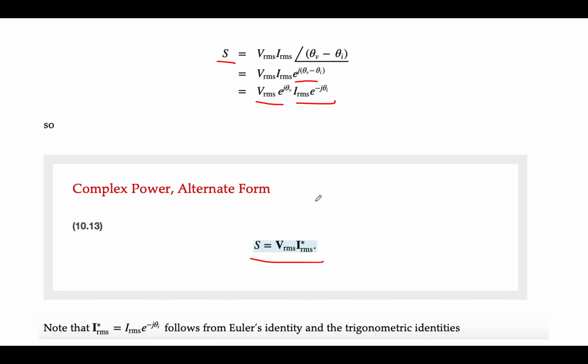In some of these expressions you have an RMS, and the bold would indicate that this is the phasor voltage. In other expressions, you'll have terms that are the magnitude. Notice the difference. This one's in bold. This one is the magnitude and carries with it a phase angle.